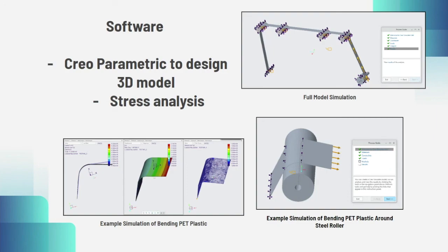Software. A critical component of the project was to understand how polyethylene plastic, used as a substrate, deforms under tension produced by friction in the rollers, the torque of the motors, and any other unforeseen contributions. In order to get an understanding of these forces, Creo Simulate Light was employed to quantify and graphically display the bending and deformation of the plastic under certain forces.